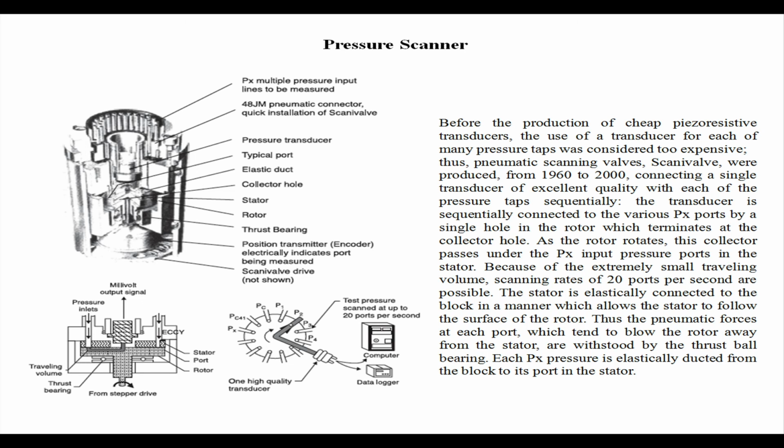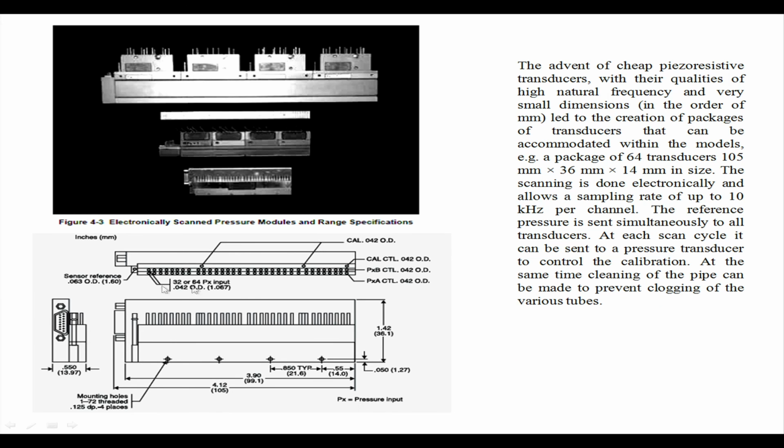Moreover, there are physical limitations to the number of ports that you can scan every second. Beyond a certain limit, there would be increasing errors coming in, and you would probably not manage very high frequency data acquisition. So there could be limitations by virtue of the design itself. Many of those issues have been overcome over time, but economics played a big role. And today, fortunately, we have systems of this kind where we have a large number of pressure ports and a matching number of pressure transducers, and they are actually so-called multiplexed.